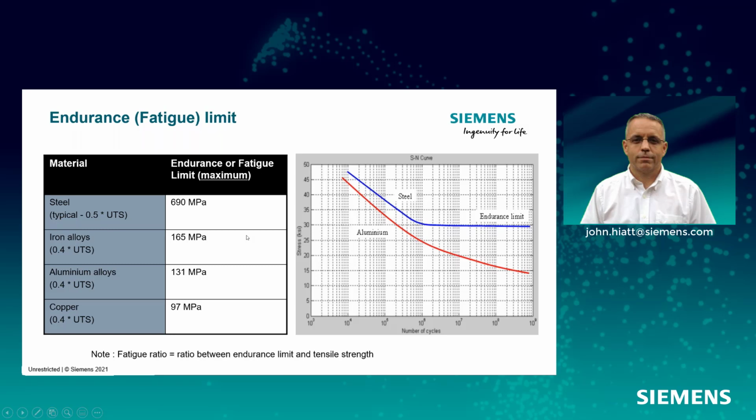The reason this is important is some people, when they want to accelerate a test, they'll increase the amplitude. So if your loading environment's starting up here and you increase by 2, it's not going to end well. It's not going to be a good test. So when you increase the amplitude, you want to look at 10%, 15%. Again, here's the aluminum curve. So if you're doing infinite life, they just got to pick a value out here.